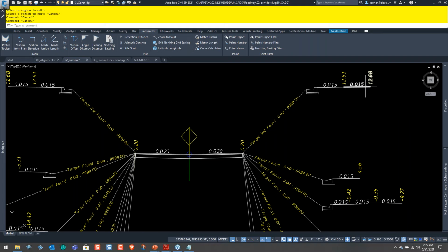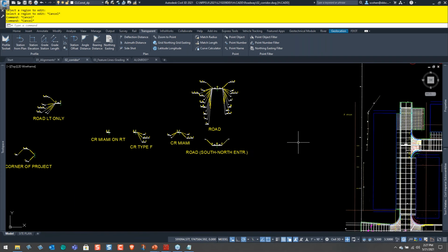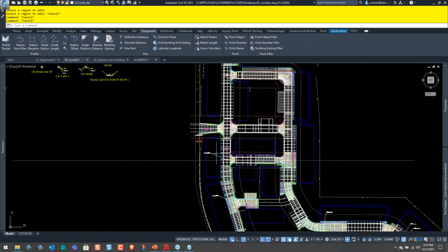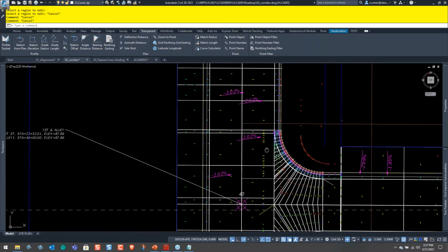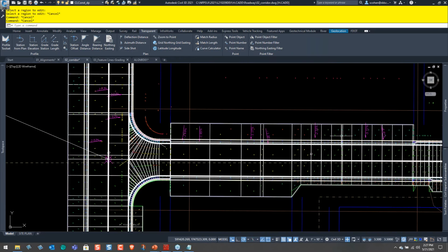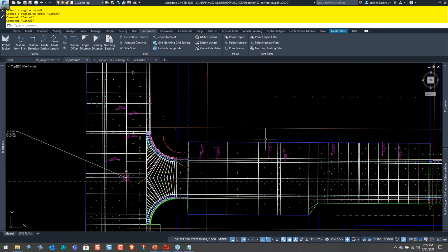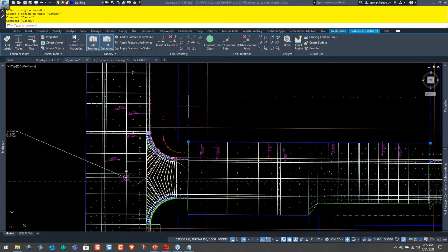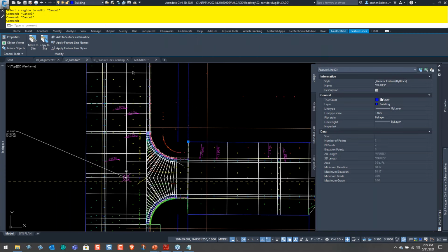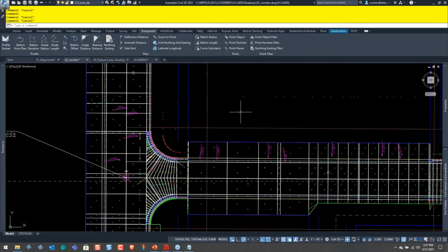because I have a range for my driveway. My range is 2 to 14%. That's DOT standards, okay? This is for the city of Ocala, and they actually say just follow the DOT standards. So to do that, again, these right here, I'll show you a little bit of what else I do. So here's a building pad, right? If I select this building pad, I basically have all these four corners, these four sides, and these are all feature lines at the same elevation initially. Once I get into fine-tune grading, I might change the side slopes or the side buildings, because obviously this is for the driveway. In fact, let me just show you that here.